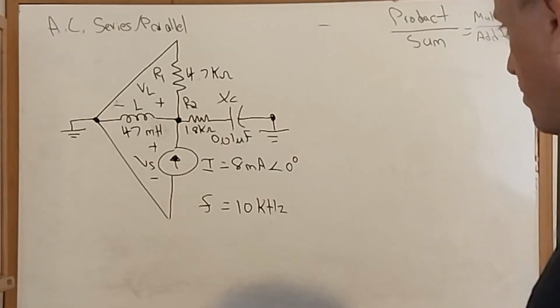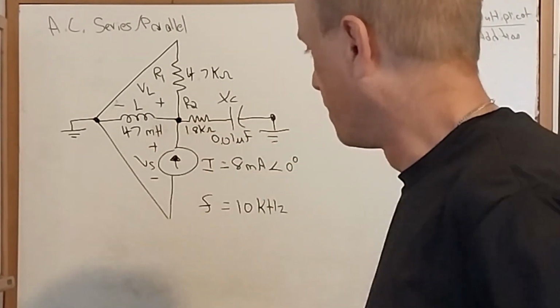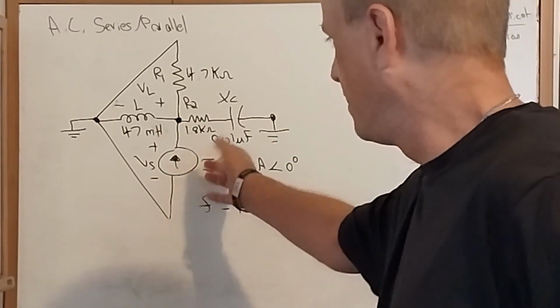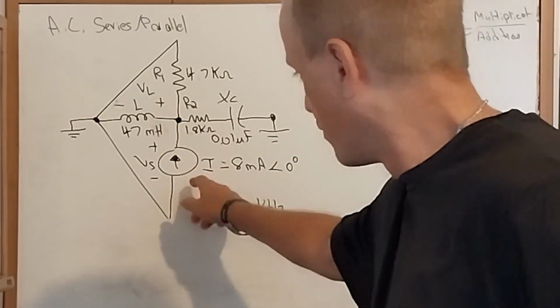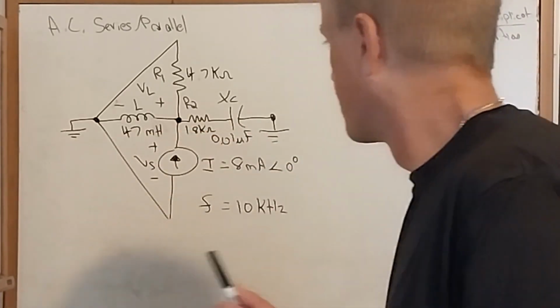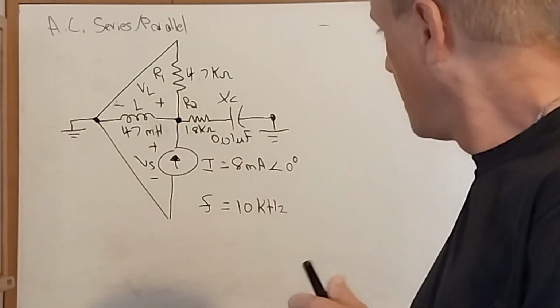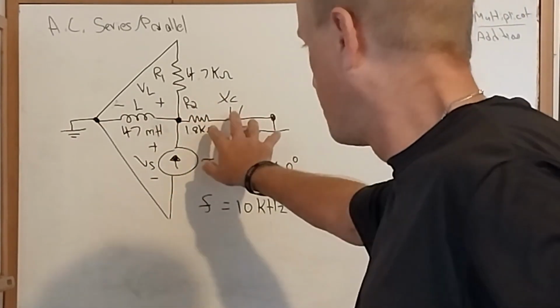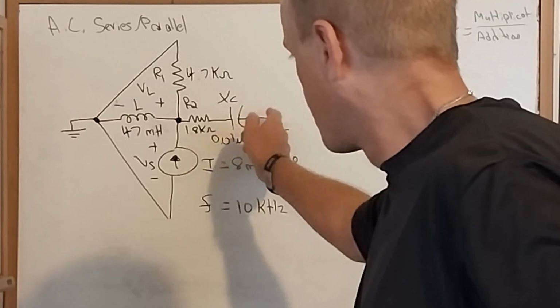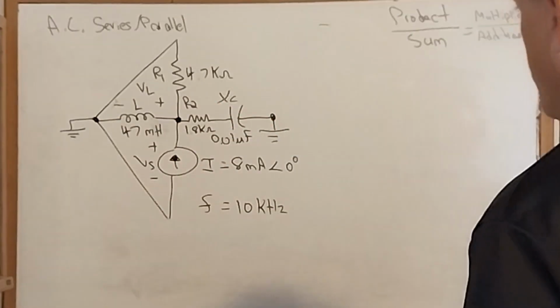Okay, this is a good problem to work on because it might be really difficult to analyze when you're looking at a DC and AC source for current or voltage. But we notice there's two ground symbols, and each of these elements, besides these two, are in series, so they can be combined into one element. Let's call these two elements together Z sub 1.